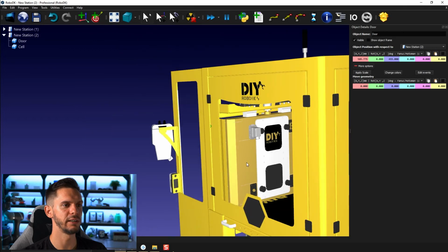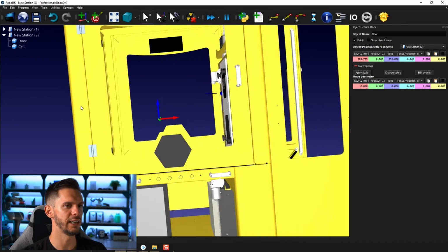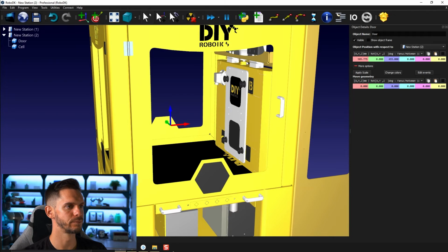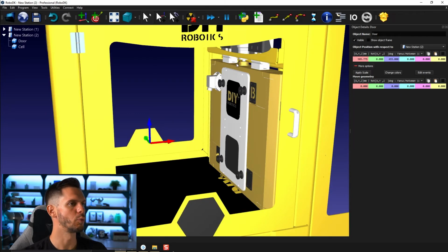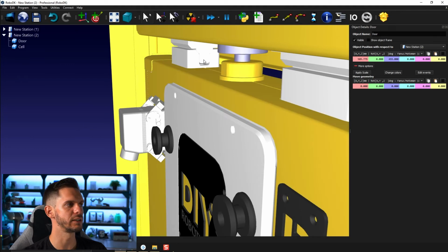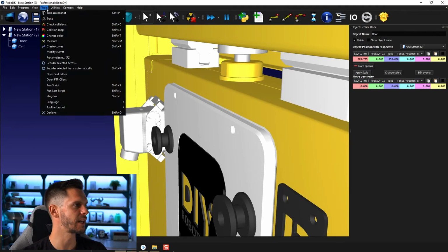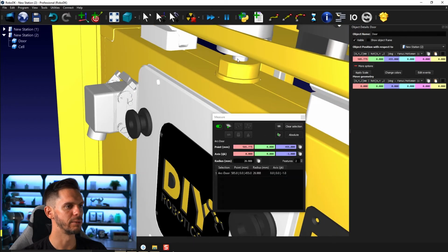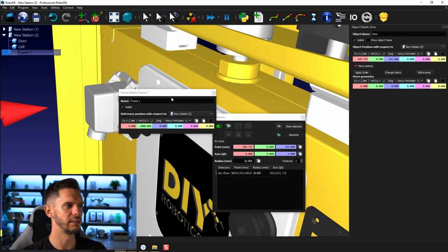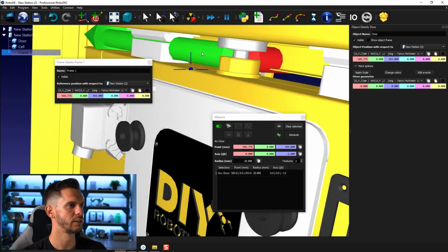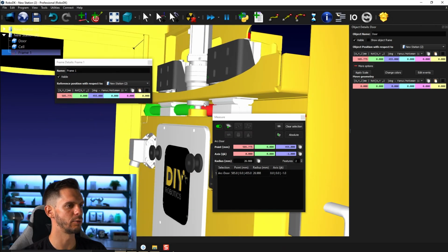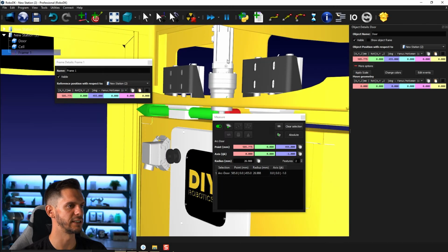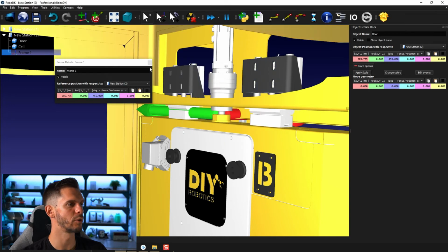Now I can close that here, and I can start creating my rotation frame. So once again, the rotation frame will be here. I already have it in my clipboard, but I'm going to measure just so that you guys see exactly what I'm doing. I'm going to measure the center point here, copy, create a frame, and then paste the value here. So the frame is right here. You can see here we have the x-axis and y-axis. So the z-axis is aligned with the center of rotation, which is what we were looking for.